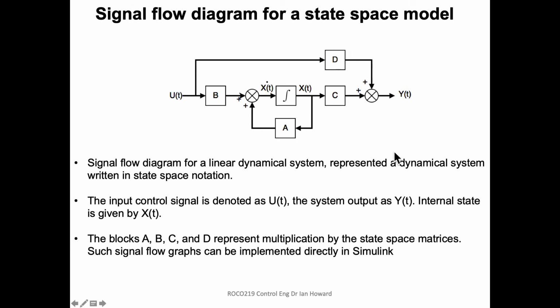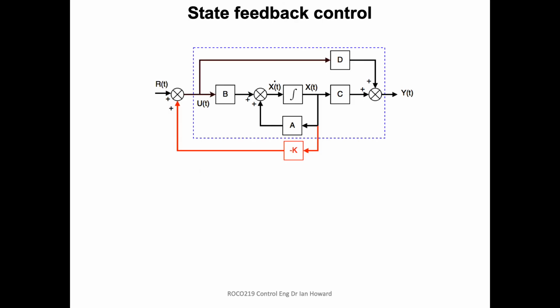I shan't go through that in too much detail because we've already covered that. And like I said before, you can directly type that into Simulink because it's a signal flow diagram, so you can actually virtually implement that directly within Simulink. And when we add state feedback control, so we feed back the full state, we can easily show that on this kind of signal flow graph.